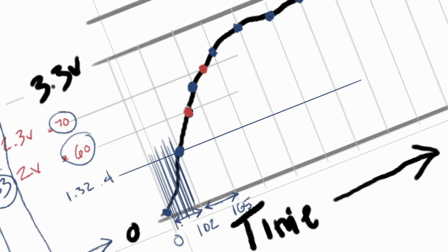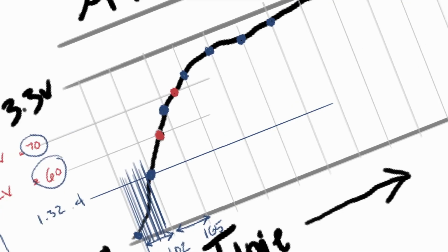There could be a whole bunch of clock cycles between this, but it needs those clock cycles to do one conversion. I believe that number is 17 microseconds, which is what I'm going to start doing in the beginning programs. I'm going to use about 17 microseconds, which is actually a long period of time and is one of the periods of times you can use in the analog to digital converter.